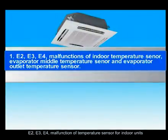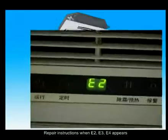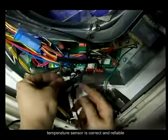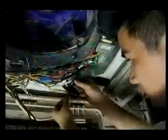E2, E3, E4, malfunction of temperature sensor for indoor units. Repair instructions when E2, E3, E4 appears. Step 1. Check if the cable connection of the indoor temperature sensor is correct and reliable. If the connector is normal, please go to the next step.